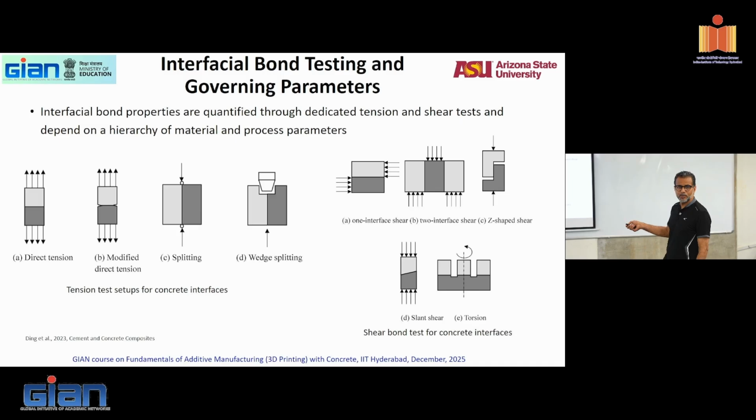Slant shear, very commonly done. You do lots of slant shear testing. Anybody who does any repair material testing, you always do slant shear testing, right? To find out if the repair material bonds well with your old parent concrete. Very same idea, you can do that.